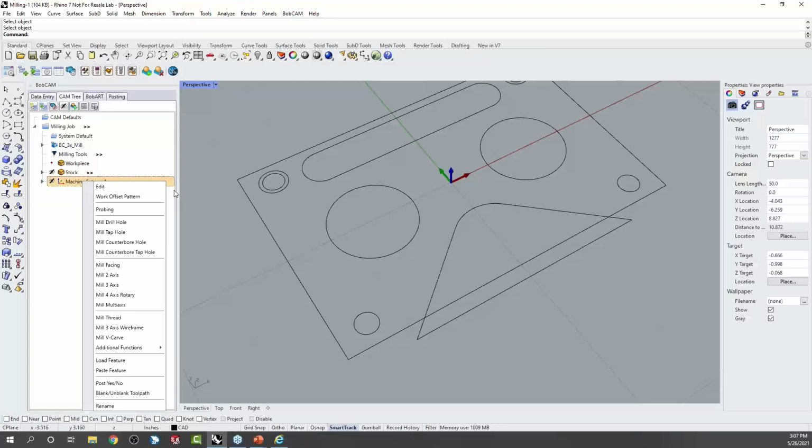So this is an intro, and I focused on some of the basics like turning and milling. I didn't really get into a lot of the 3D milling, where I believe a lot of our powerhouse functions are, especially as we continue to move up the line. When we're talking about 4-axis, our 4-axis standard package would offer indexing, wrapping, and rotary. And then our 4-axis advance package, 4-axis Pro, would include all of that plus surface-based toolpaths. Now, if you're dealing with a post or some other irregular shape, like a furniture leg to a chair, any of those scenarios would work well.